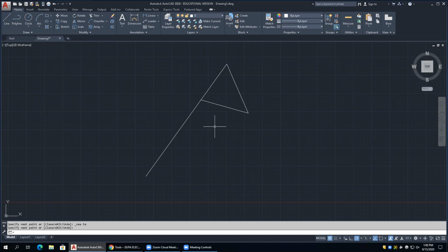You also have to give it a base point. So think about that as being like you're sticking a pin right at that point, and that's the point about which the rotation is occurring. But that pin, I could stick that pin up here, I could stick it there, I could even stick it over here. So where you give it the base point doesn't have to be on the object, but I'm going to tell you probably a good 80% of the time it is. Okay. Otherwise, the rotation will be kind of strange if you come off of it.